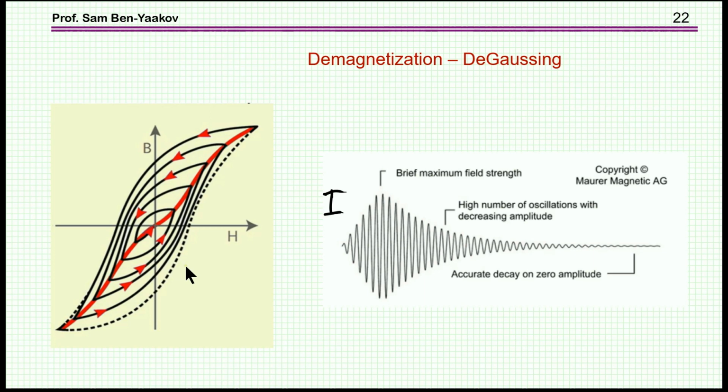The possibility is that if you do have a problem of hysteresis and remanence here, due to the fact that you expose the sensor to very high current, high field, you can demagnetize it or degauss it by feeding in a current that starts high and then goes lower and lower and lower. You will find it maybe as a button on current probes with the Hall effect that are doing that in order to reduce the hysteresis error. That is, then when you work in this area, you will not have this large error.